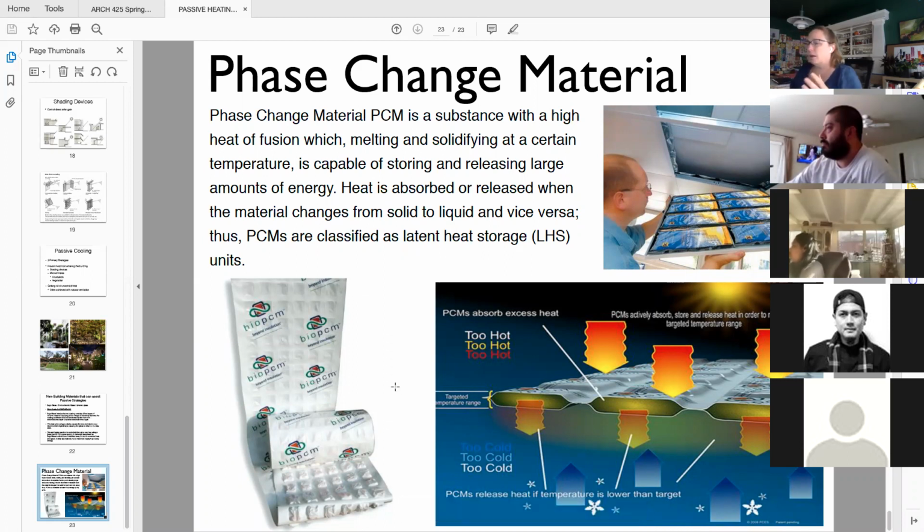So again, keep in mind, heat is always going to migrate to try and stay at equilibrium. It's going to go from hot to cold or from cold to hot. What determines how long that takes is the thickness and the property of the material, and making sure you put your materials in the right place, or your insulation in the right layer, or create your air gap where you need it so you don't get conductance.